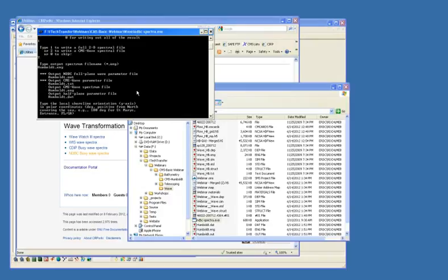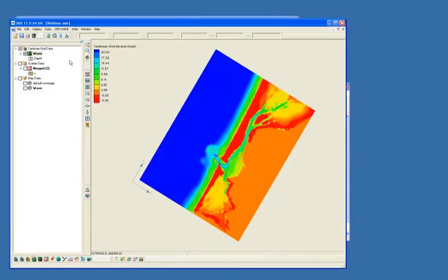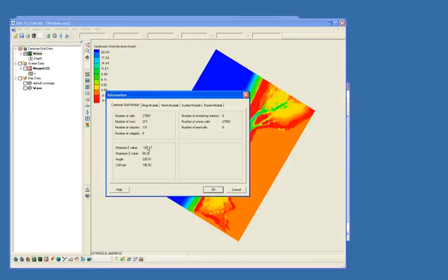And then it's asking for the local shoreline orientation in polar coordinates. This is something that you would get from your grid. You would find out what the orientation is. It's under File, Get Information. There's a certain orientation that it gives here, this 328.91.